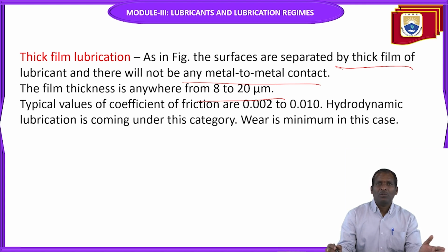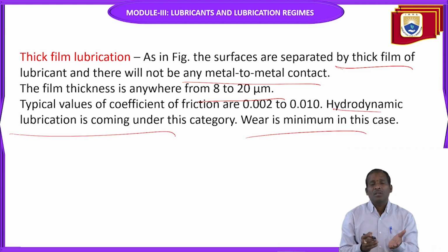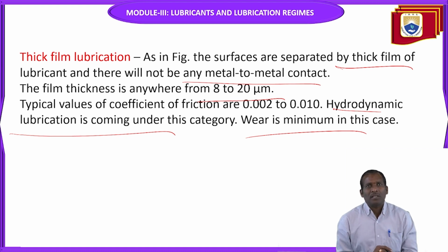The typical values of coefficient of friction are 0.002 to 0.010. Hydrodynamic lubrication comes under this category of thick film lubrication. In this case the wear is very minimal, so there are no major wear chances in this type of lubrication.